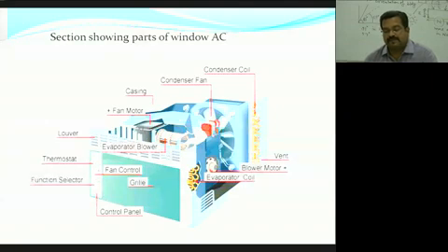And in this section you can see the evaporator coil as well. So this evaporator coil, there runs the cool gas inside this evaporator coil. So when a fan blows air through the evaporator coil, that air becomes cooler and goes inside the space.